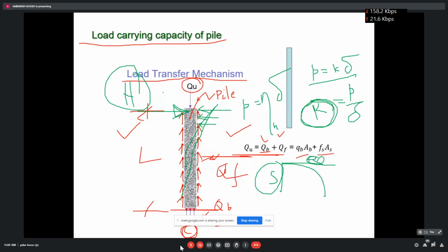So now you see, whenever we have given a pile, we are transferring the load to the dependable soil, but the topsoil we know will be weak. But when we are going for the contribution for the horizontal load, at that time we have to take the horizontal subgrade reaction of the soft soil. That's why I told you that this is very much vital regarding load carrying capacity. So what you have to know, the basic mechanism is the horizontal subgrade reaction. Horizontal subgrade reaction is vital.